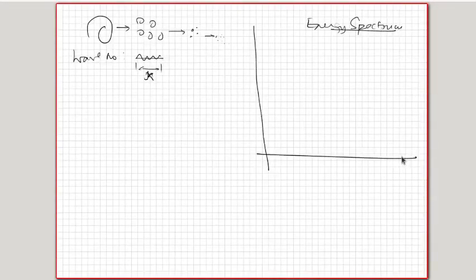So your molecular scales would come somewhere here, and the length scale of the flow would come somewhere here. So if I call this L, and if I call this, let us say, eta, which is the Kolmogorov length scale, so this is L inverse, this is eta inverse, and there would be something called a lambda inverse here, which I'll talk about as Taylor microscale.